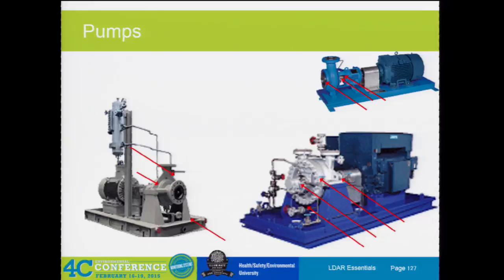And then you want to get all the little nuts and stuff that are going into that. As long as it's part of the pump body, they consider it part of the pump. I don't think I've ever seen anywhere they treat those as separate connectors. They just monitor any leaking interface on the pump as part of that pump. So those take a little bit longer to monitor than your typical valve, but you don't have a whole lot of leaking interface parts there, except the seal, a couple of bolts that usually stick through it, and a flange.